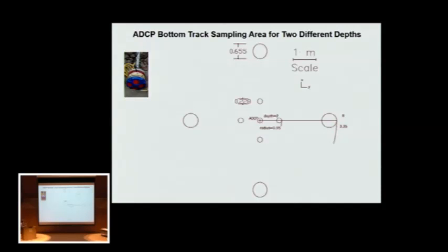The important point about this is you get only one velocity component in each of those 4 beam areas. So in order to resolve a Cartesian velocity, we need to take the one component from here, the one component from there, one component from there, and one component from there, put it through a coordinate transform, and you can then get an estimate of x, y, and z velocity. With the 4th beam, we get 2 redundant measurements of the vertical, and that can be used to estimate error.